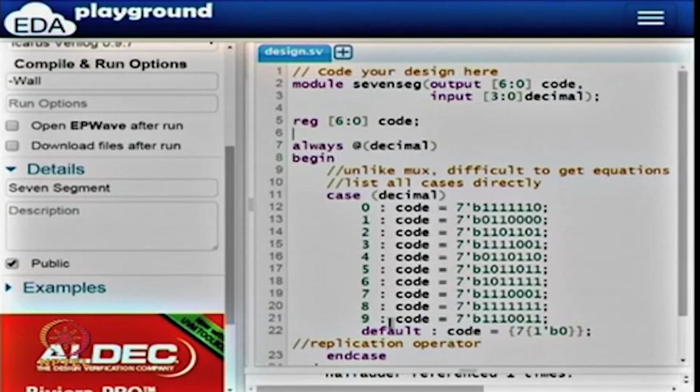Let us look at, for instance, 6. It has a vector which says one segment, the top right segment, is off, so you can see that here, that is 0. This is simple and nice, and if it is not any of the 10 cases from 0 to 9, by default code is assigned to all zeros.